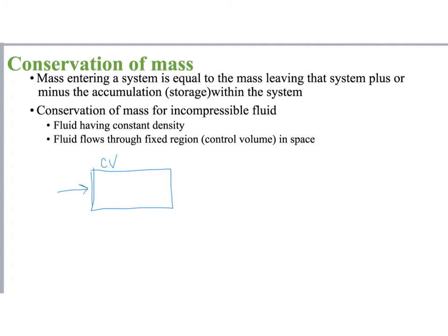It has some inflow, which we'll call I, which is a function of time. If you think back to where you have done fluids so far, like a pipe flow, your inflow would be stream flow, right, or flow in a pipe. You're going to have some outflow, and we'll call that Q. Then inside this control volume, you're going to have storage, and that is also going to be a function of time. Okay, so we're going to write what happens to the storage over time, the change in storage.